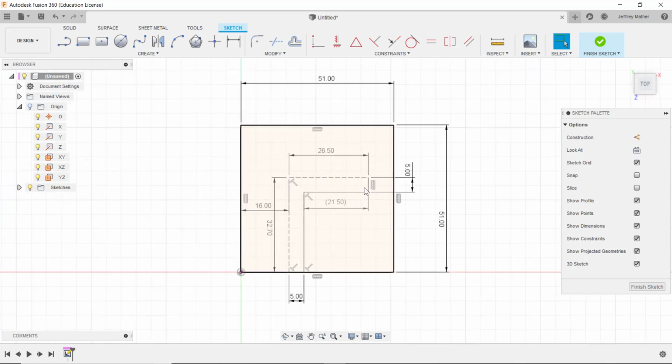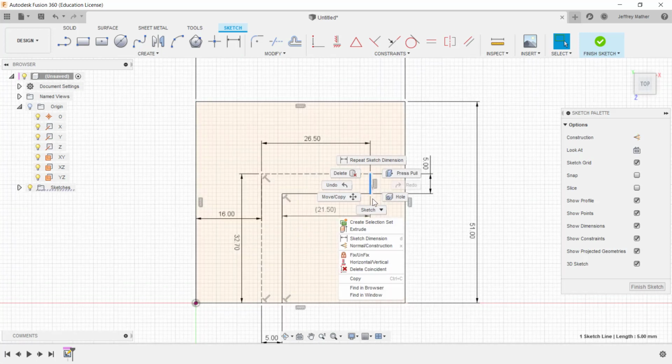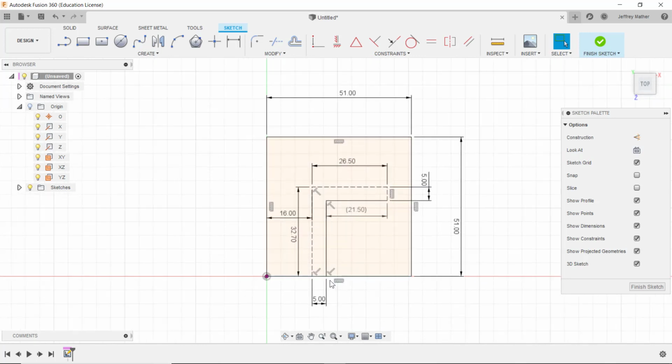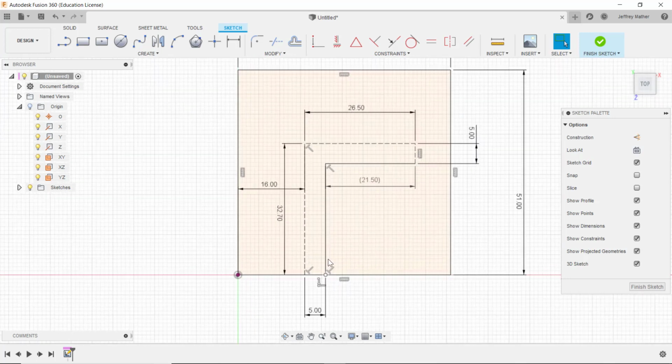Okay, now this line, I'm going to change that to a construction line. Okay. And so I have left this line and this line are object lines, and then the outside lines are object lines. Now when I'm doing something like this, I would normally do the center line path, but you haven't defined what the center line path is, or you haven't defined what the radius is here.